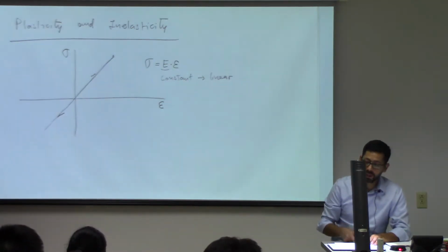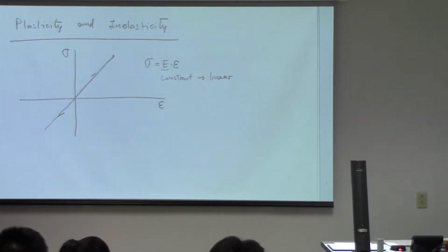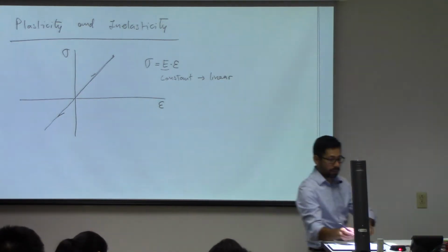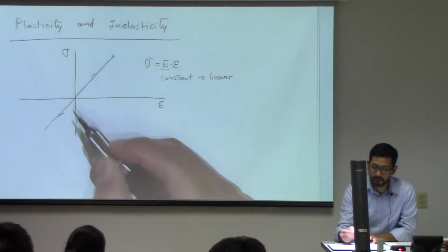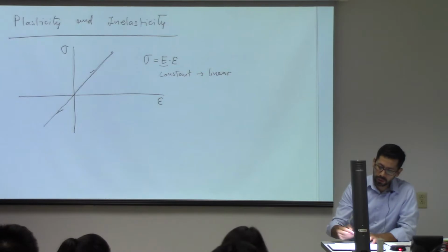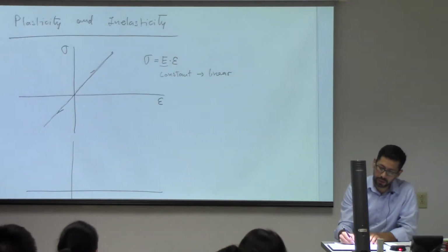then we have linear elasticity. And in linear elasticity, or in general in all problems of elasticity, the strains are recoverable strains. So you go up to this point, you decide to come back, and you come back to the same line, you can recover the strains. There are no irrecoverable strains. We didn't talk much about this problem, but you may find this in some other applications.